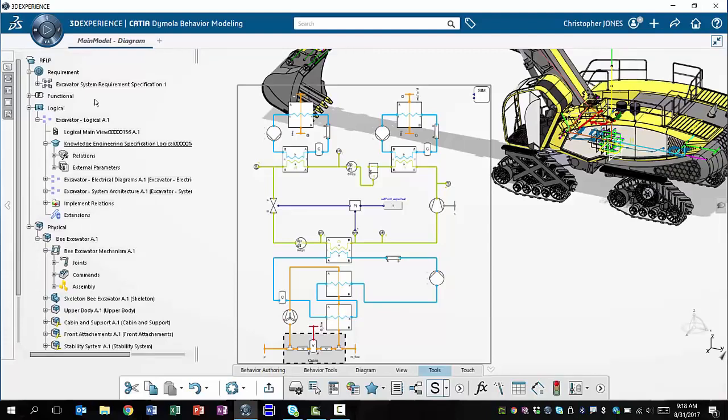Now, typically when an engineer is scaling the air conditioning system, they would be running dozens or maybe even hundreds of simulations to narrow down the parameters and settings of the system. And assuming we've done that, we might come to the conclusion that in order to fulfill our thermal requirements, we have to increase the size of our heat exchanger. So we might have to change the number of plates within the heat exchanger.